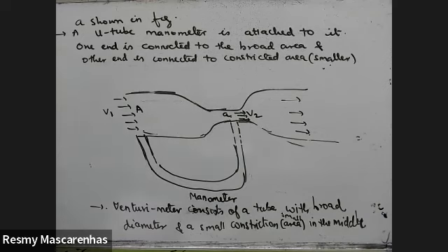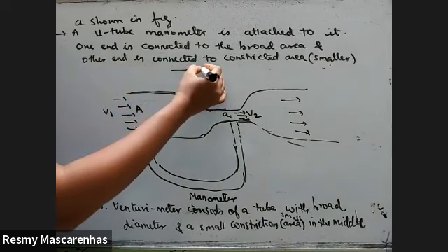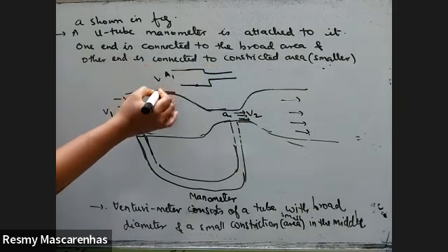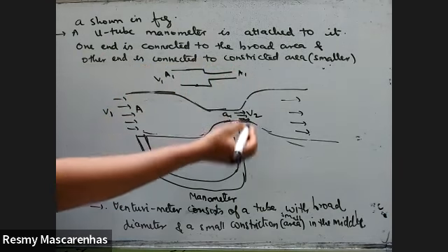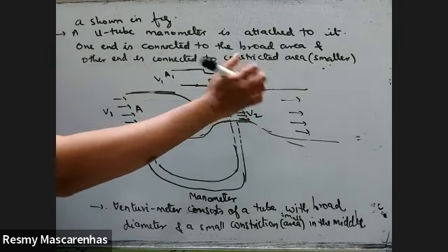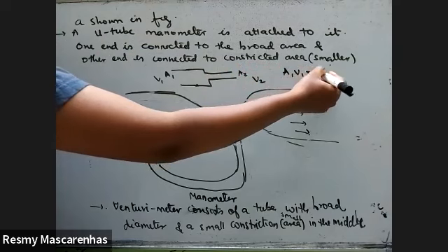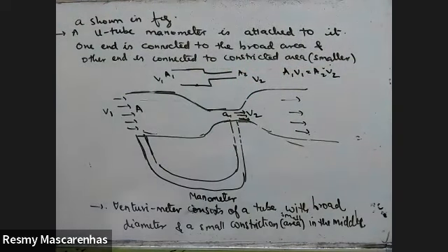In the previous class, we had seen something called the equation of continuity. Remember what I told: suppose you have a pipe like this, if the area is big, then the velocity will be small. If the area is smaller, the velocity will be more. Why? Always A1 V1 should be equal to A2 V2. I've given you an example also of a water pipe in the garden. When you try to block the tip of the pipe, you are reducing the area.